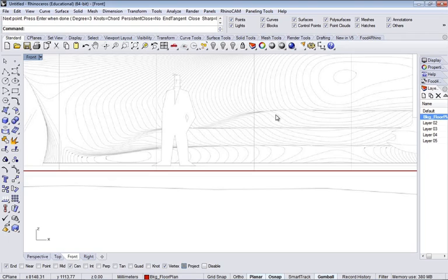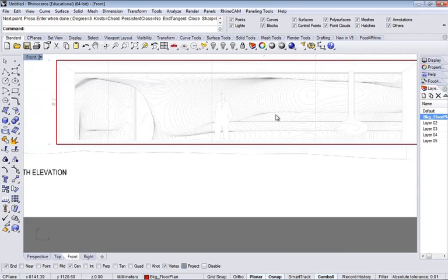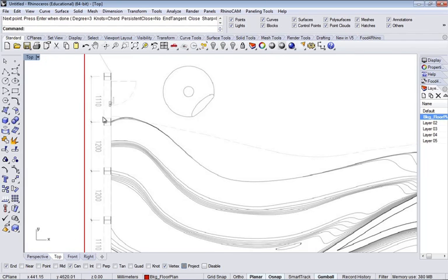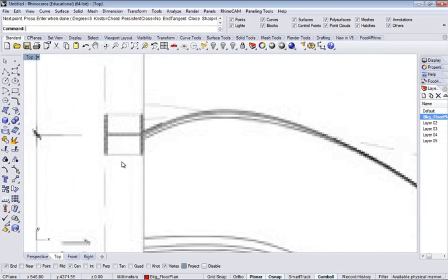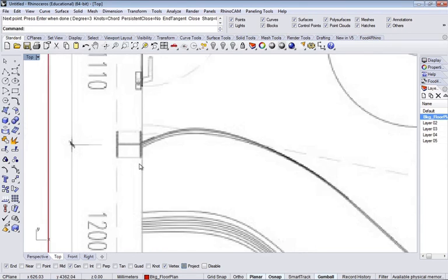So it's probably not going to be all one operation. It's probably going to be a couple of surfaces that you start to patch together. And we'll go over that in a little bit more depth. And I'll go into using blocks. So when we use the wide flange beams, columns here, we can build those up as blocks, which then are instances that allow us to make one change to one of them, and it will change all of them together. So anytime we need to go back and modify, it makes it much more robust.